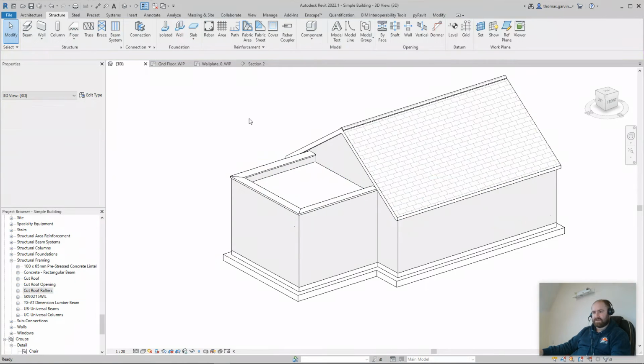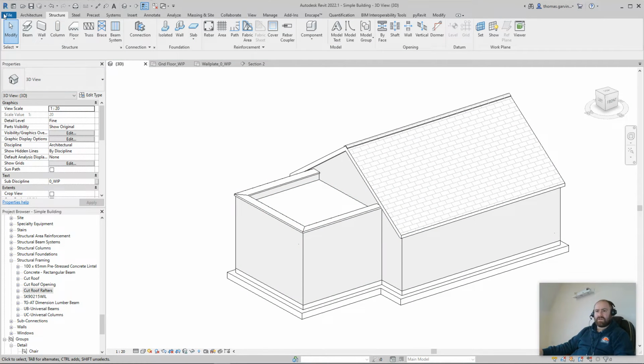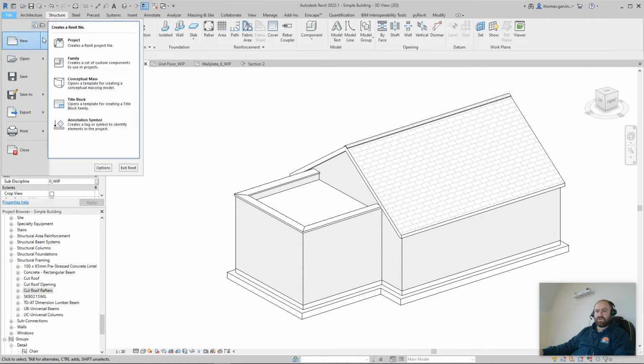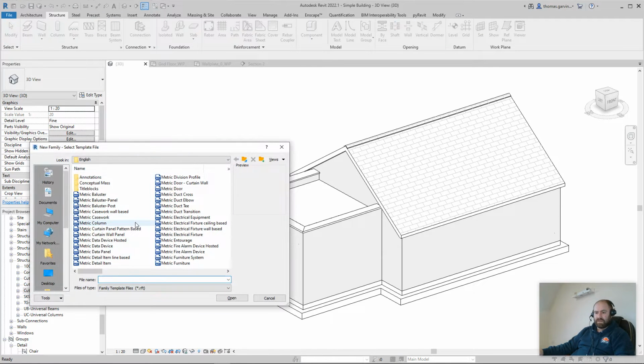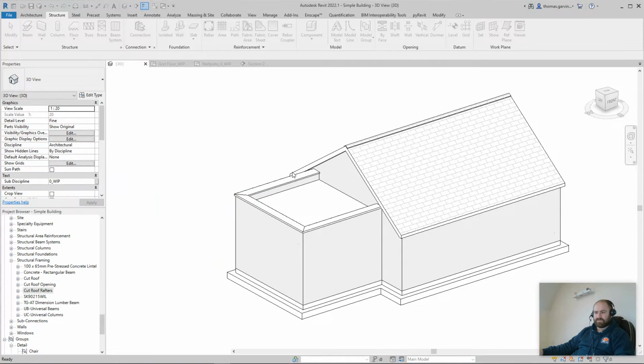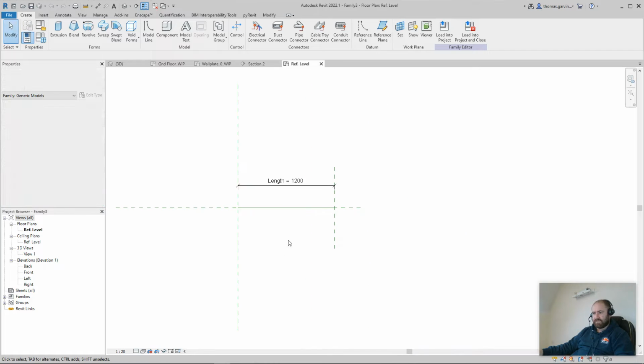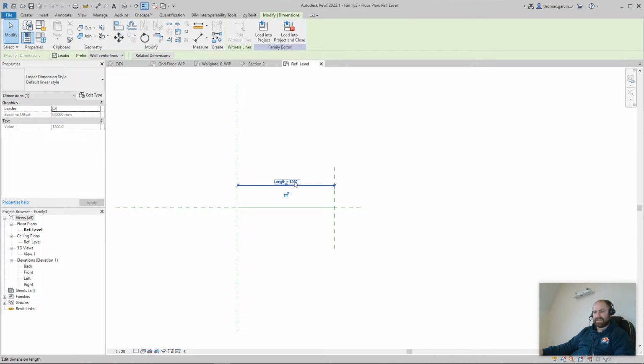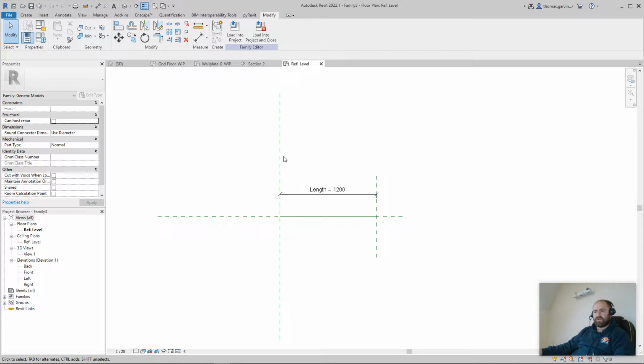Okay. All right. Escape. I'm going to go ahead and go to File and New Family. Scroll to Generic Model Line Based. Where are we? There it is. Open. Okay, so this has a length parameter already set in it, and it's an instance parameter, so that when you place it, you kind of draw a line, and it'll extrude whatever your shape is along that line in your project.